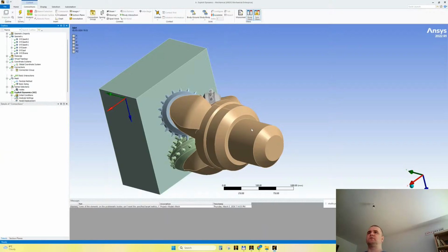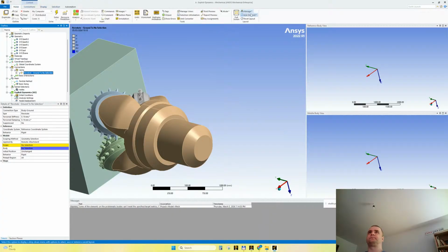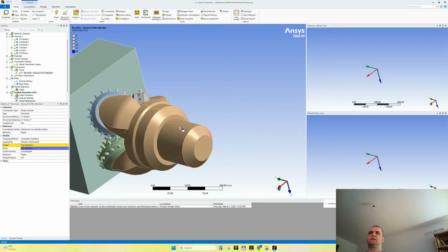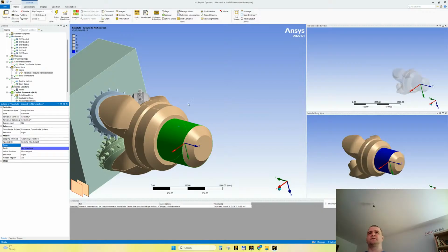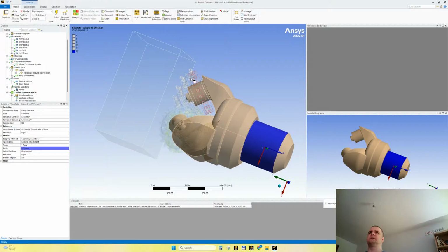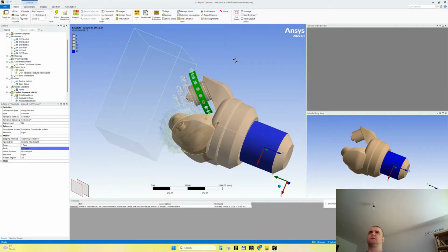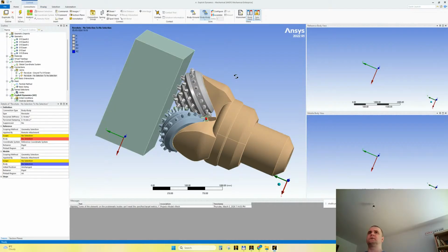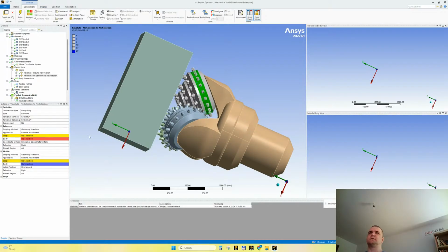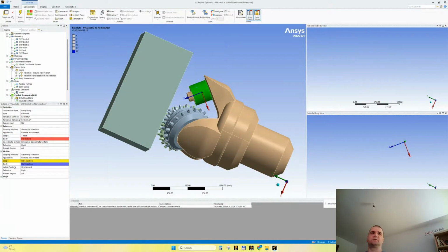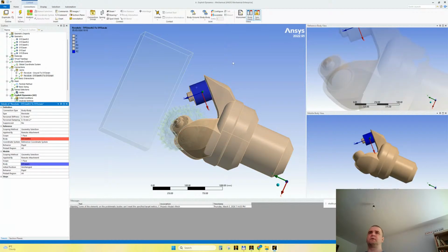All right, so I was thinking about having a body ground revolute joint for this face. Change the selection to single select. Change cursor mode to face. And I would like to rotate this main fixture and assign the rotational joints between. So body revolute, and we have this on one side and this on the other side. We have one revolute joint.